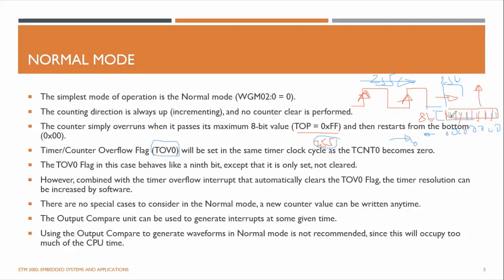If it reaches 255, next cycle there won't be 256 because it's 8-bit. It's not going backwards. What it does is just restart, set this timer to all zeros and count again from 1, right? So it's a timer reset.